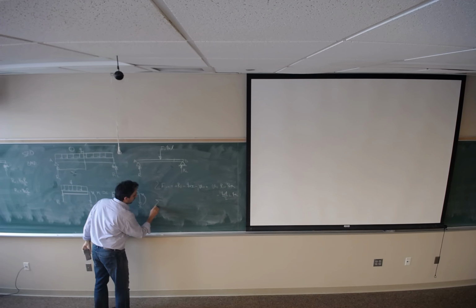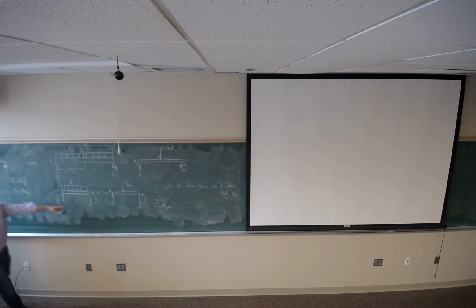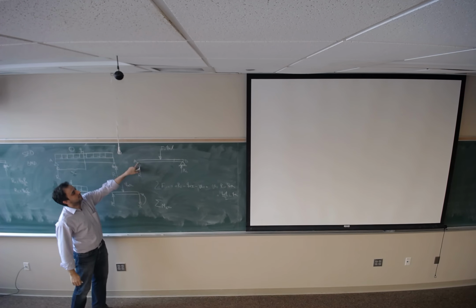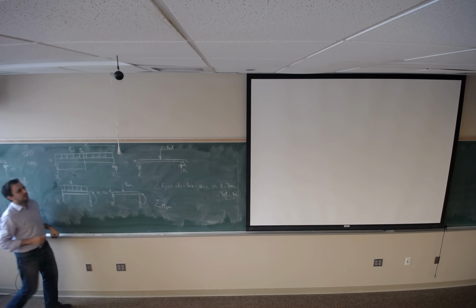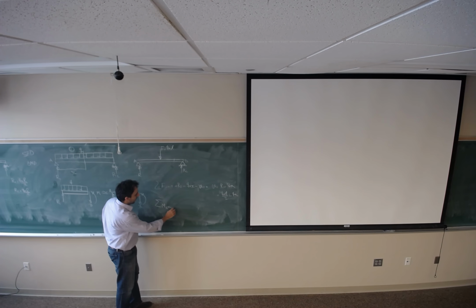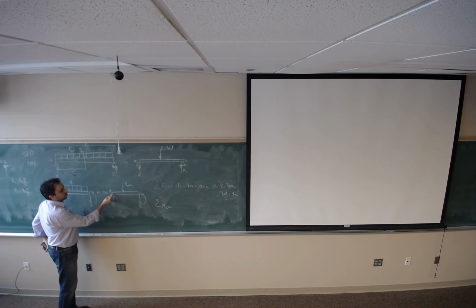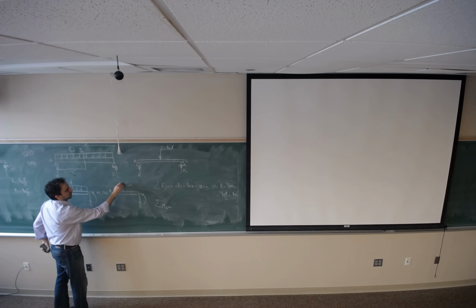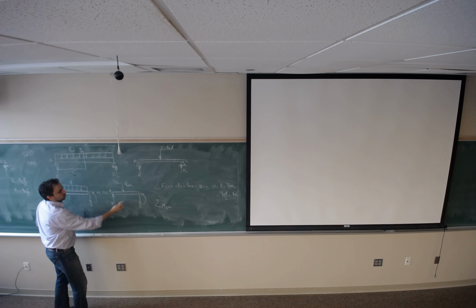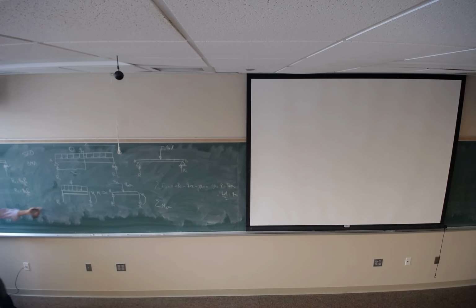So we said the summation of the moment about point A equals 0. Why does it equal 0? Because it's not rotating about point A, and point A cannot support any moment. So the summation of the moment should equal 0. This force doesn't make any moment at this location because the distance from point A is 0. This force is making Qx times X over 2. Half of this section is going to be X over 2.